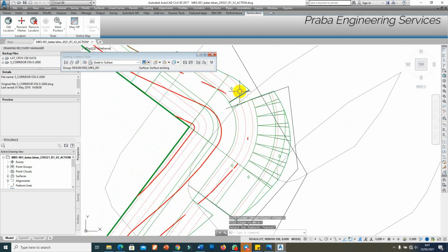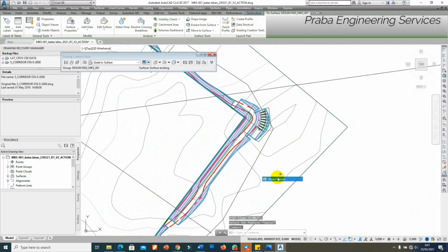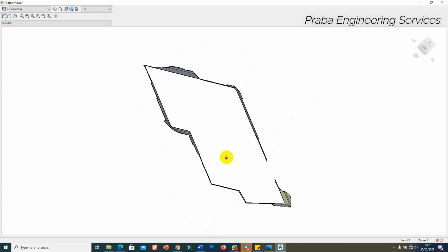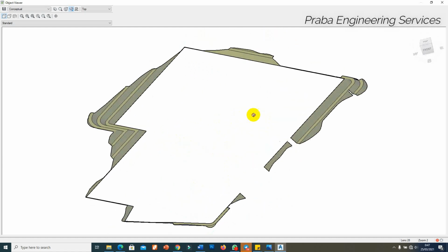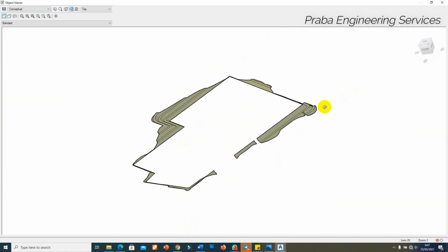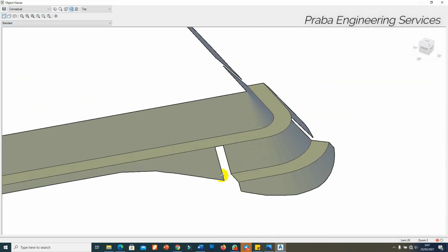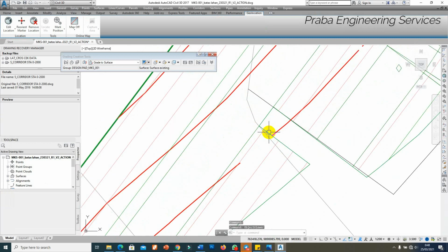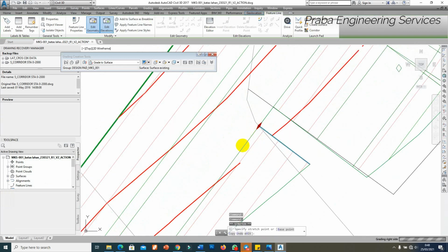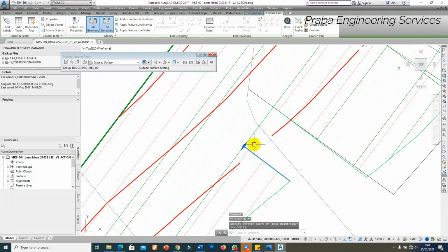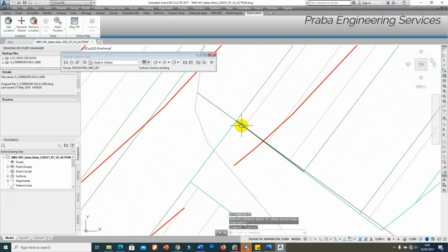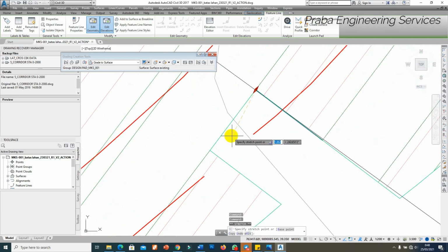and like before we need to add some additional line by grading feature line. Here is one. When you check very detailed, make sure this is less than 3, so when you have some location more than 3, you can shifting by click this one to this one, okay, like this. If it's too wide, we can adjust it like this one too.